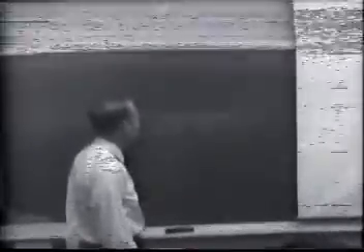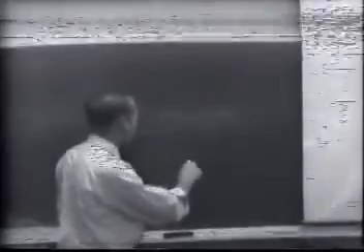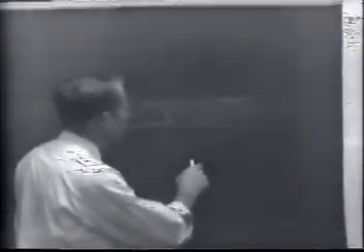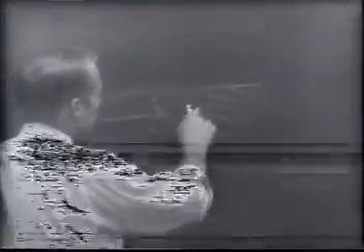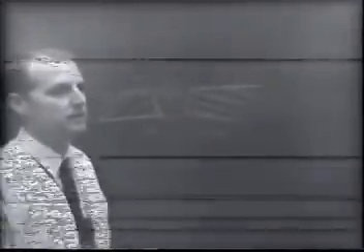Another way to lengthen this arc is by a magnetic field. As we know from some of our other previous basics, if we have a conductor in motion in a magnetic field, we can get a force in a given direction. And with proper location of the magnetic field, which we'll get into later, we can make the arc move in one direction or another. Any kind of a heated conductor, a heated column of air or gases, would tend to rise. So we'd like to make the arc move in that direction.